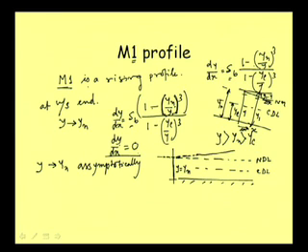So this is one characteristic of the M1 profile, that at the upstream end the depth rises very slowly, because the gradually varied flow line is meeting yn asymptotically. It will be increasing very slowly, and that is why the length of the M1 profile is quite large, because it will take a lot of time to meet yn, the uniform flow depth.